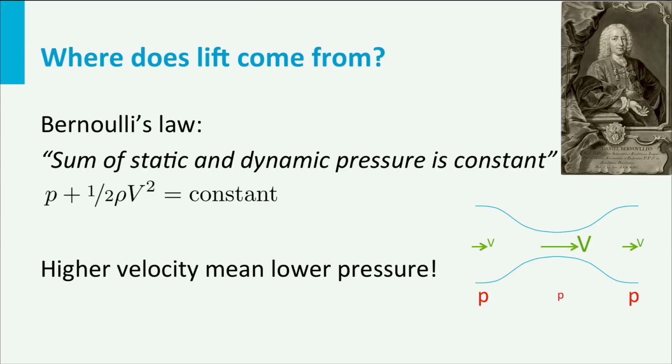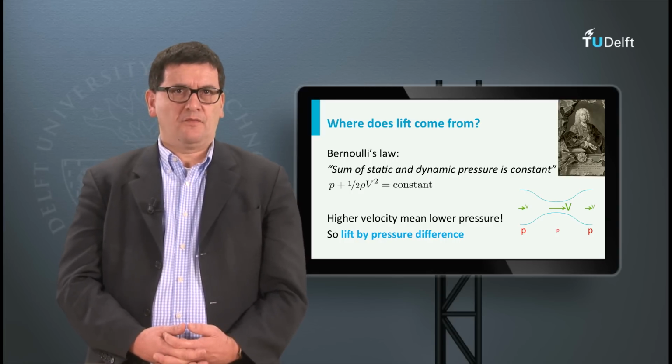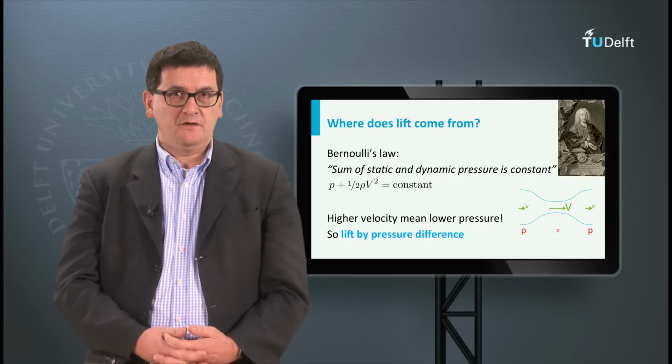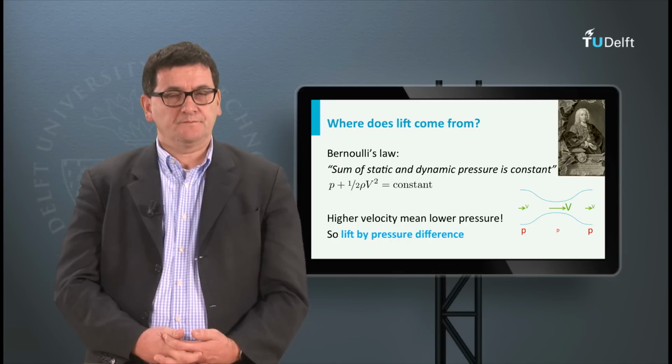So in a tube with a throat, the pressure in the narrow section is the lowest, but the airspeed is the highest. This explanation tells that pressure differences can be created by differences in airspeed. These pressure differences can be used to create lift. Note that Bernoulli's law is applicable for particular situations only, for example for low airspeeds and incompressible media.